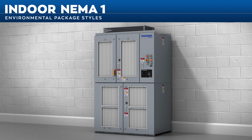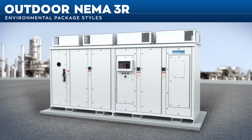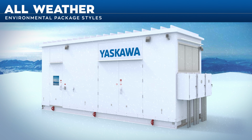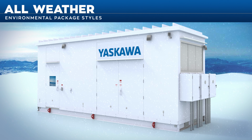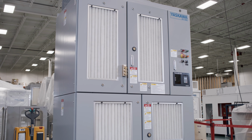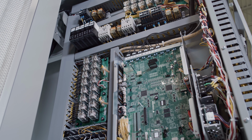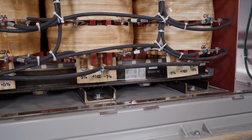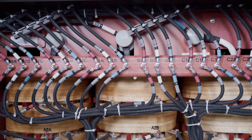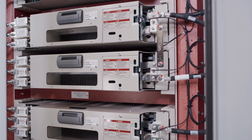Medium voltage drives can be packaged for indoor use, general outdoor use, or to withstand the most extreme outdoor climatic conditions. While each application has a different look and different construction, each drive is comprised of the same basic building blocks. A multi-pulse transformer ensures clean power quality. Modular power cells provide precise sinusoidal motor control.